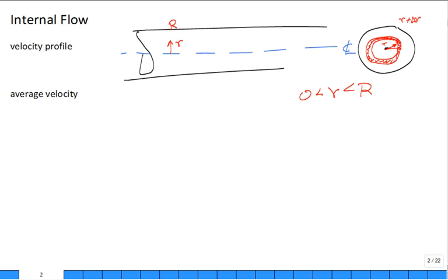Often our velocity profiles, almost always, I can't think of any case where it's not, are just one-dimensional, and we would sketch it by the velocity profile looking like this, where you talk about u, that's the speed u as a function of r. Well, u is down in this other direction. Maybe you call it the x direction. Maybe you call it the z direction. Often we call it the x direction, down the axis of the pipe. So u is the velocity in the x, so maybe u sub x if you wanted to emphasize that, or just u is a function of r.